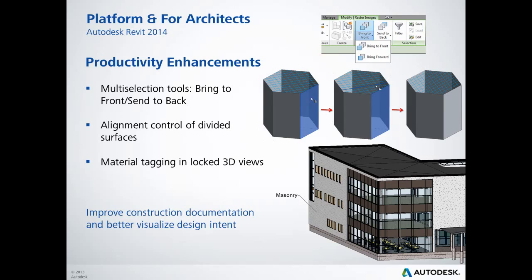In Revit 2014, you can select multiple detail items or import raster images and use the send to back, send backward, bring to front, or bring forward tools to move them all in one operation.